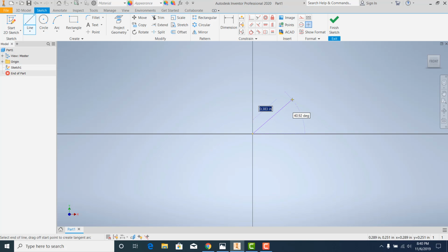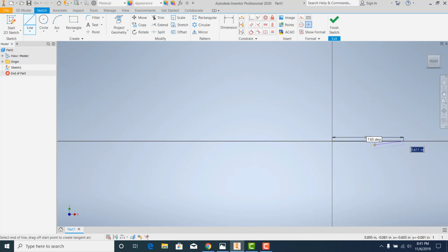The blue highlighted box is able to be entered in with my numbers. So as I pull this thing this direction, it will snap to that line. You gotta be careful that it's not at a slight angle. Make sure it's sitting right on the line. Then I'm going to manually enter 1.5 because I had 3 blocks across, 1/2 inch, 1/2 inch, 1/2 inch. So 1.5 is what I'm going to enter into that spot, and you'll see the thing went off of the edge of the screen.